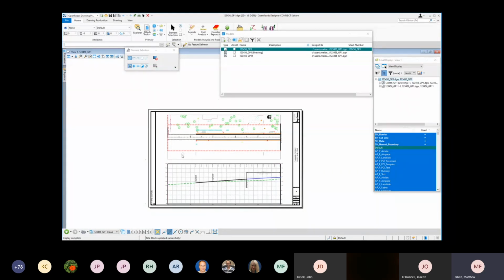So that's pretty much the same workflow, except that we create a container file first and then use it to create our name boundaries and then create the sheets from there. All of the annotation and things, as I said, would be placed in the drawing model. You might have some random notes you might add in your sheet, and that's fine too. But this is probably the recommended workflow for 9 out of 10 types of drawings that you're going to want to create.